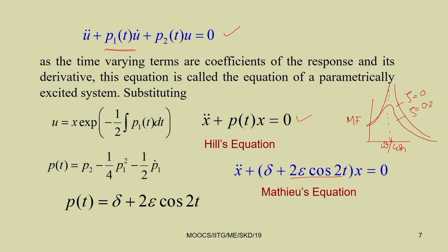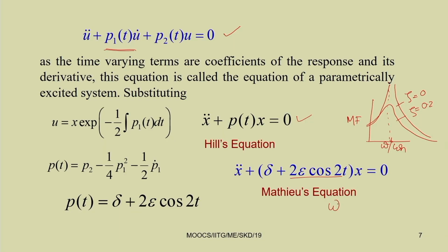But in the case of parametrically excited systems, you can observe that when the external frequency is away from the natural frequency, then you have the resonance condition. For example, when omega equal to omega m plus omega n, you can have the resonance condition. What are m and n? For example, m equal to 1 and n equal to 1, so this becomes 2, and omega equal to 2 omega 1.